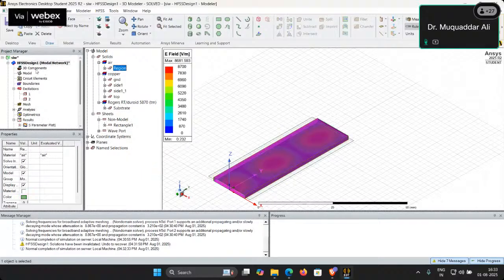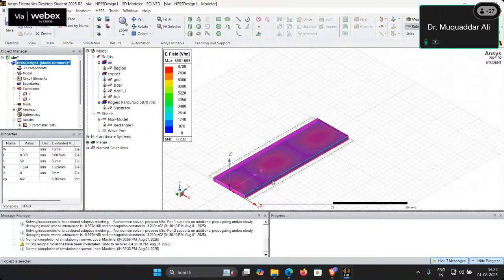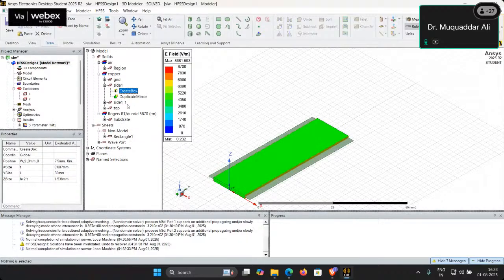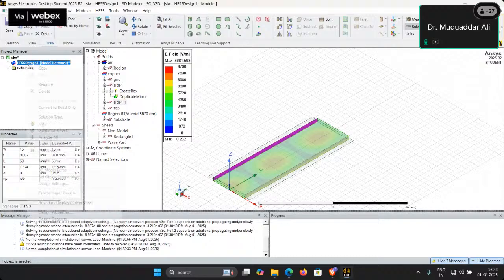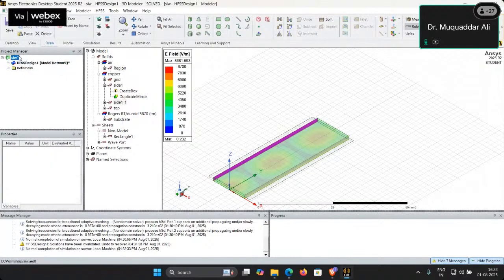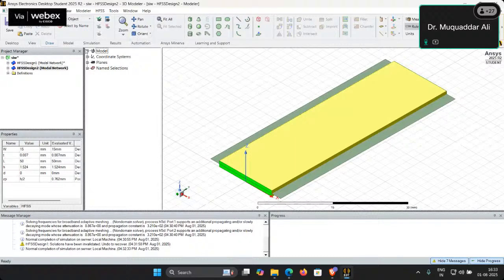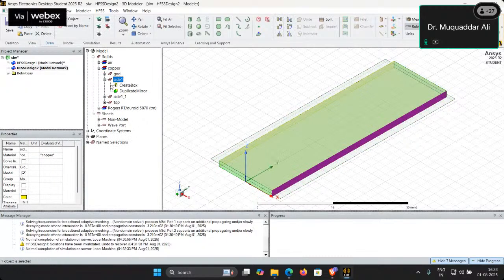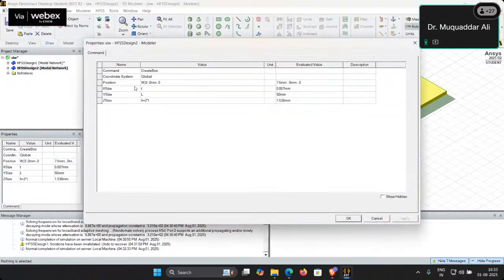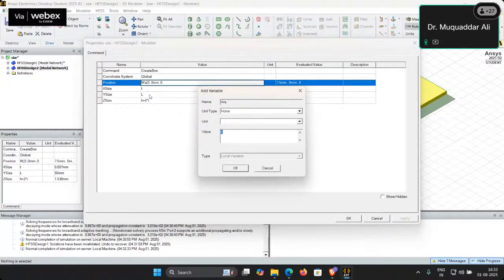Now what we need to do, we need to move this waveguide. So instead of creating the sides, these sides, let me copy this one and click paste. Now what we will be doing, first we select these sides and move the side to inside the substrate. So let us say WA, and WA I am selecting as 12 mm.